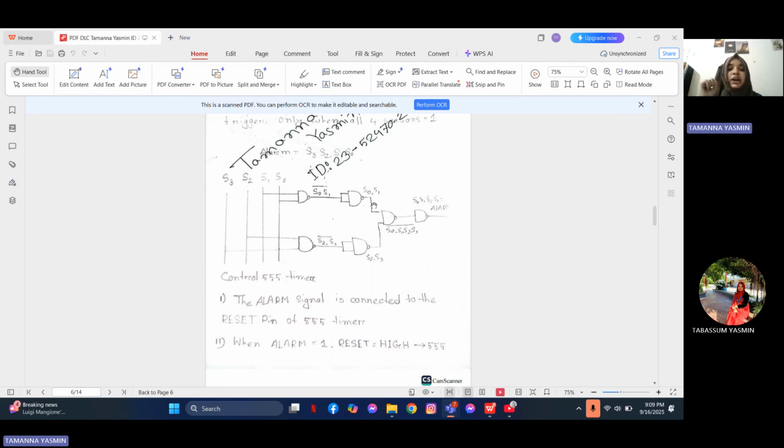The requirement was to implement this using only NAND gates. Since a NAND gate is a universal gate, we can build any other logic function from it. To create an AND function from NANDs, you simply invert the output of a NAND gate. So I designed a circuit where the four sensor signals are fed into a single four-input NAND gate.